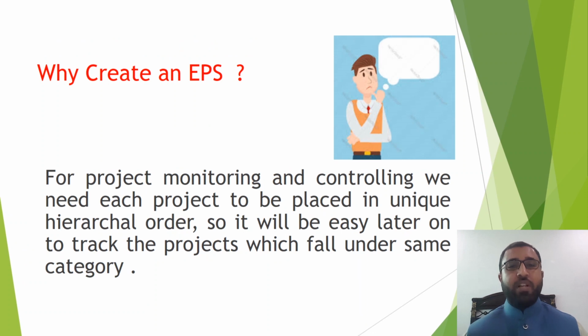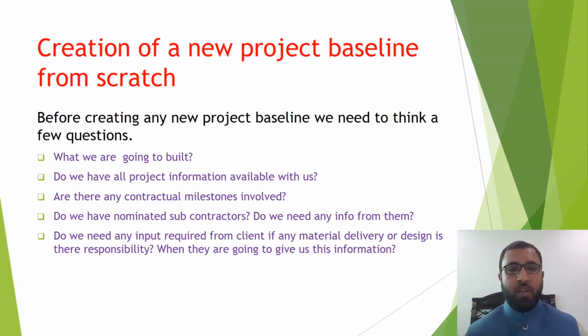So this is the question that I already spoke about. For a project, why do we need to create EPS? For project monitoring and controlling, we need each project to be placed in a unique hierarchical order, so it will be easy later on to track the projects which fall under the same category. So before the creation of the new project baseline, let us create the EPS in P6.